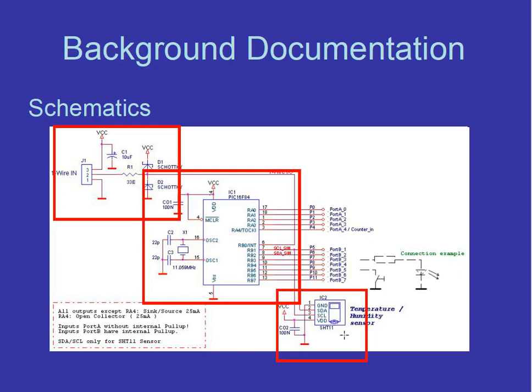If it is totally off, then you have to get into that particular portion of the schematic or circuit, and then troubleshoot what happened in each component. The same process you will do for each component, for example measuring input and output, and seeing if you're using the same rating. That kind of stuff you will find out.